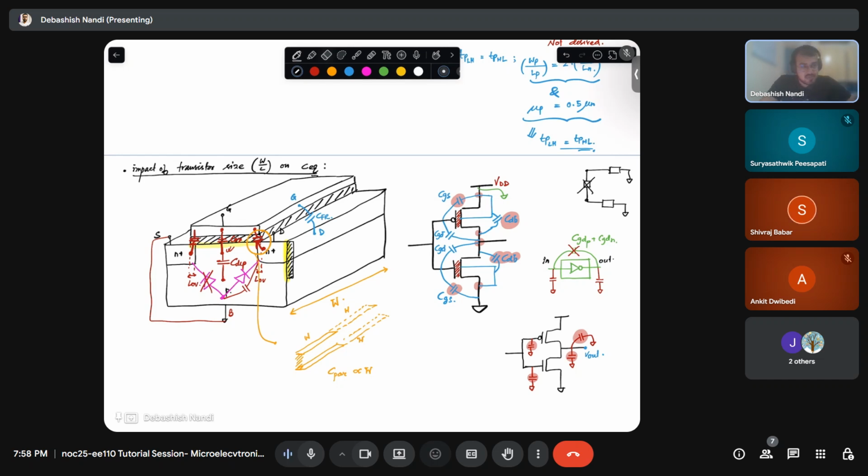So anyway, we are placing the input capacitance of the inverter and the output capacitance of the inverter. What I am telling you is, I have these capacitances, right? See, CGS and CDB are sorted because these are connected from a node to ground. Fine. But what about this CGD? CGD is connected between input and output, right? This node to this node. So how will I bifurcate this between input side and output side?